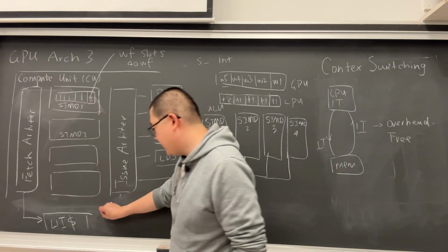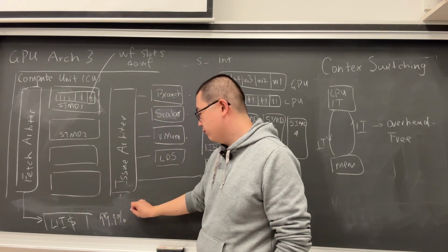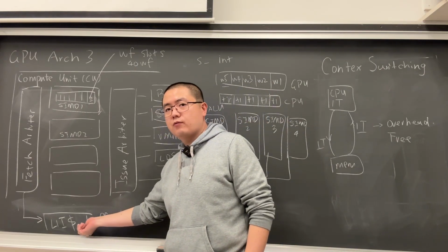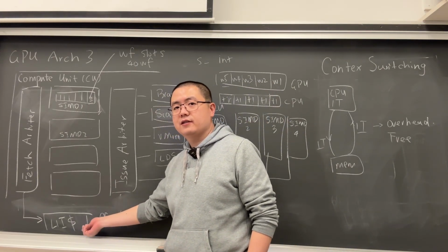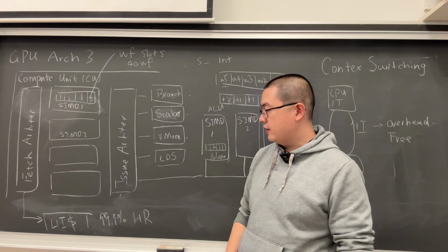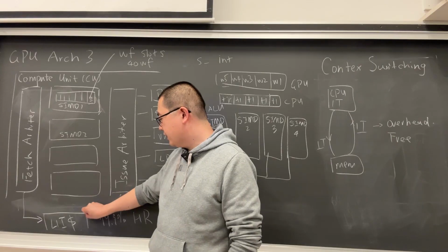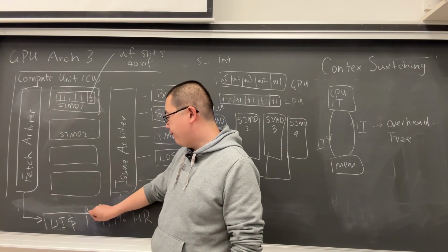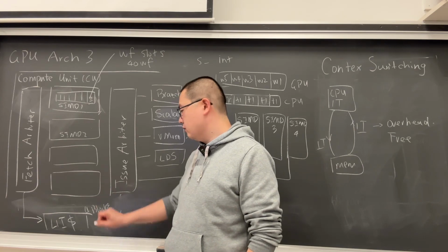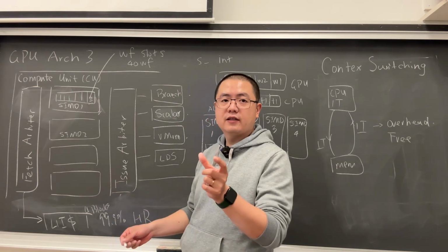So it has something like a 99.9% hit rate, right? So if this is like 1 or 2 cycle latency, it's not a big problem. It can pump instructions very quickly. And in the AMD design, each L1I can provide 4 blocks, where a block can be something like 32 bytes, okay?